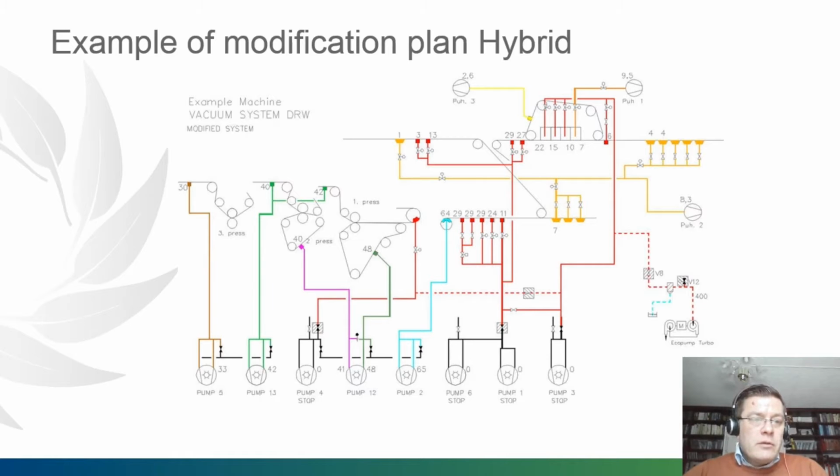If we are mixing liquid ring pumps and turbo blowers in the same system, we call it a hybrid system. This kind of system can be beneficial practically only in rebuild installations, where investment can be reduced by leaving some of the old liquid ring pumps running parallel with the turbo blower. Usually, liquid ring pumps are dedicated to the high vacuum positions where liquid ring pump efficiency is at its best.